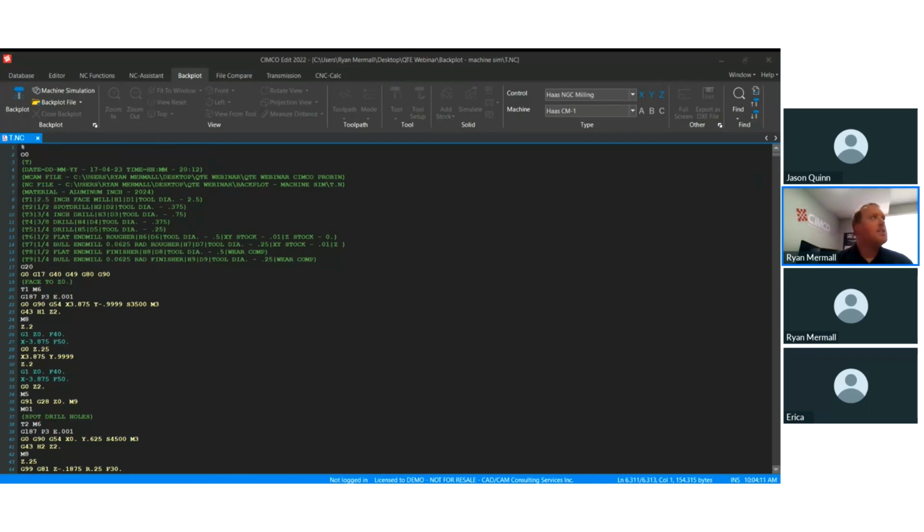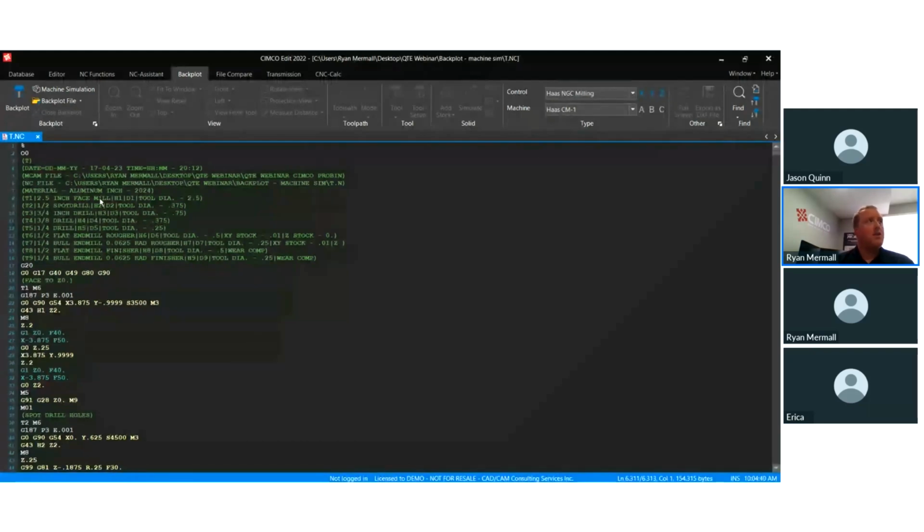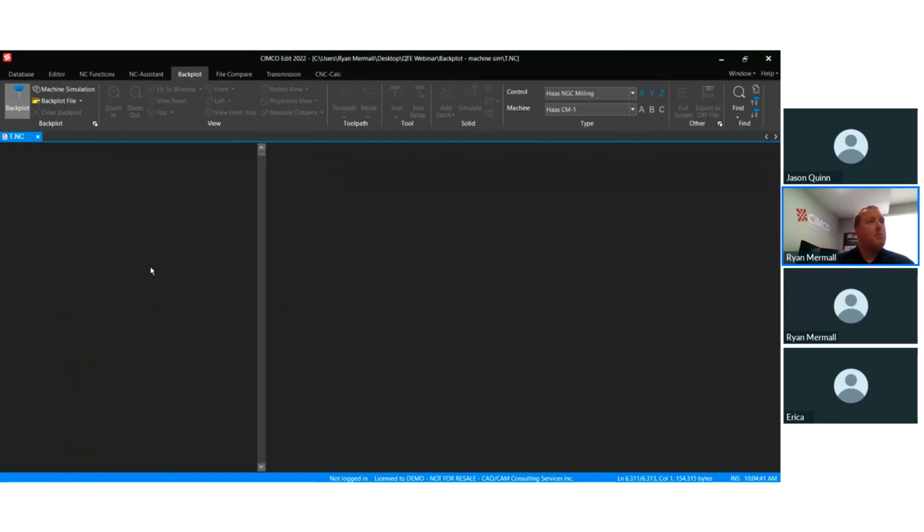As you can see within this window, we can certainly pick the specific machine. We can tell the different pieces of information, such as my workpiece, the fixture, the stock, enter everything to it, of course. What that'll actually end up doing is creating a number of files within a folder. In that particular case, we have our G-code file along with what we call our setup file and STL files within there. When I go ahead and actually launch the backplot and or machine simulation, it's actually going to be looking inside of that folder for the STL files, of course.